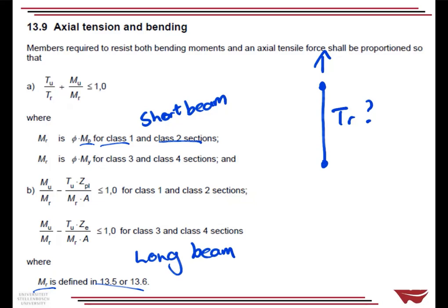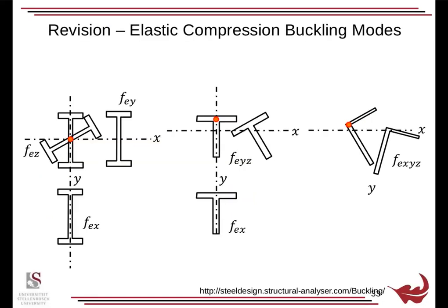And remember, the tension resistance is not based upon lengths. You don't have multiple tension resistances. You'd look at just where the minimum tension resistance is, and use that, either gross or net section, etc. So that brings us to the end.